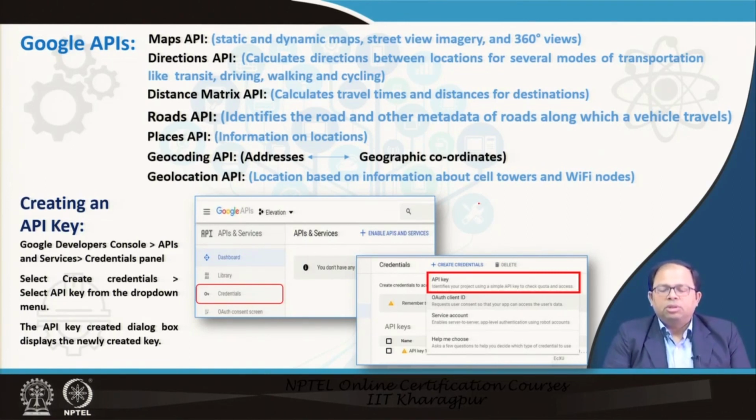Directions API shows us the way a particular transportation mode can travel between two locations. For example, we can determine the starting and ending point of a trip, or the actual route a person follows during a particular trip, using this API. So we have chances of integrating these systems with existing land use transportation models to do better visualizations, as well as to get feedback like existing travel time or congestion levels in a particular corridor. This could be integrated in our land use transportation models.